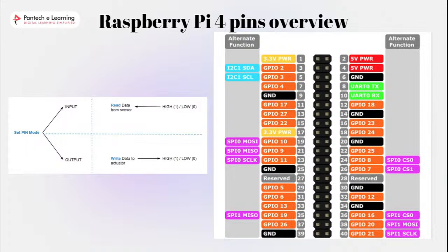Now, this is all about the digital pins. Now, GPIO's voltage. All GPIOs work at 3.3 volt. It's important for you to know this in case you need to plug in a component with a different voltage. Sometimes you will find sensors that are powered with 5 volt, but all the communication pins run at 3.3 volt, right? In this case, no problem.